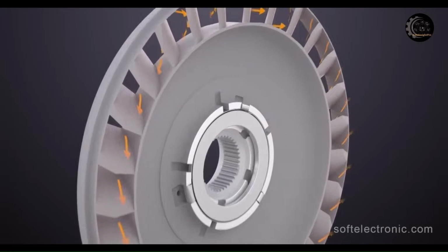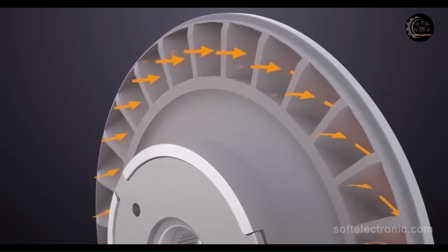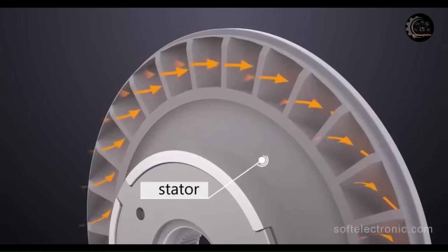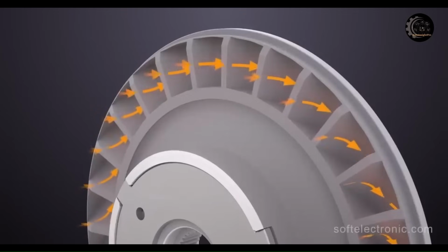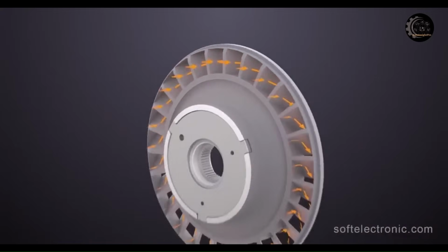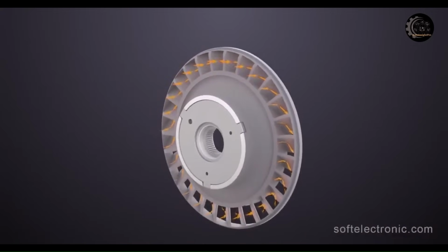The stator is a stationary component located between the impeller and turbine. Its purpose is to redirect the fluid flow exiting the turbine back to the impeller, improving efficiency and increasing torque multiplication during acceleration.